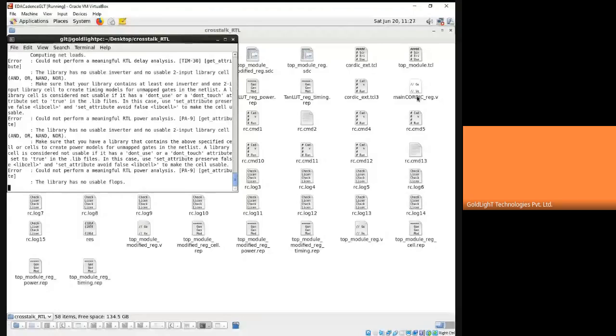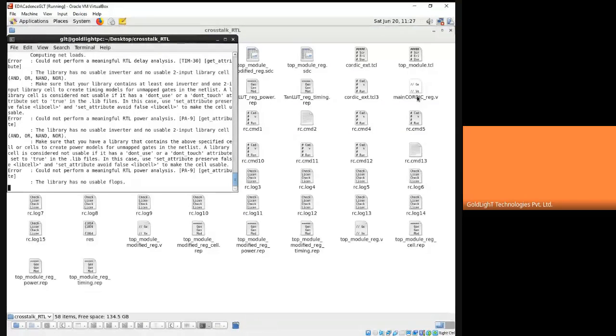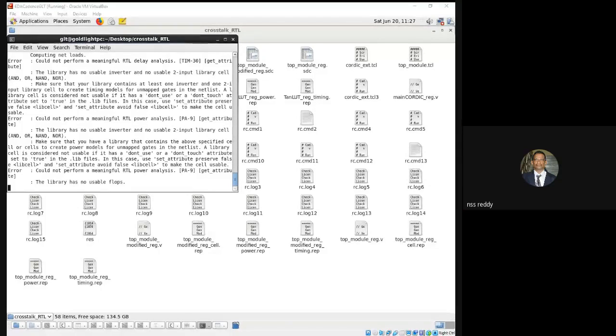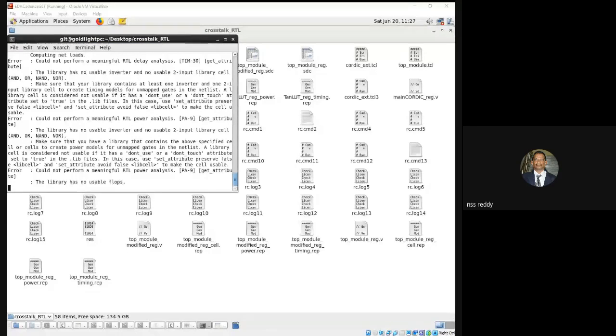For that, the CMOS EDU website is better. Detailed information is available there. CMOS EDU, I will type in the chat. A lot of very good information is available. Separately, you can take a transistor and vary the DC, that is, study its DC characteristics. From that you can find out the active region and the bias condition, everything. Okay, sir. Thank you, sir.